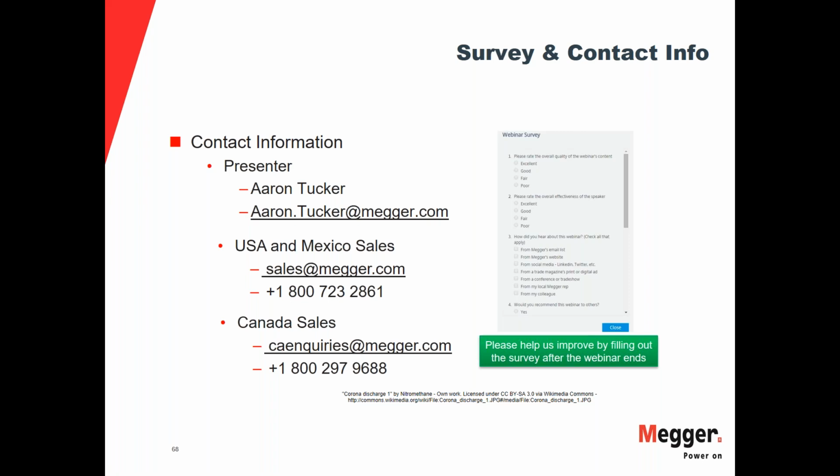Okay. The first thing is, when you come out to the field, you need to look at the nameplate of the transformer. The most important thing, especially using this three-phase connection type instrumentation, is to make the right connection to the right terminal.